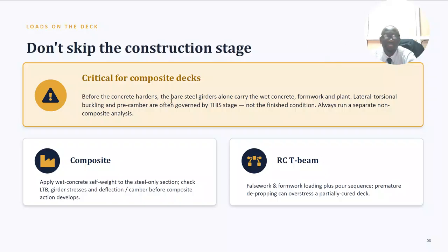Always run a separate non-composite analysis. Very important. Now, I've seen some of you designing a 20 meter span and going in for a composite approach. The good thing is the software does the non-composite and the composite for you. Now, the engineer is saying he wants you to do it by hand, manually.